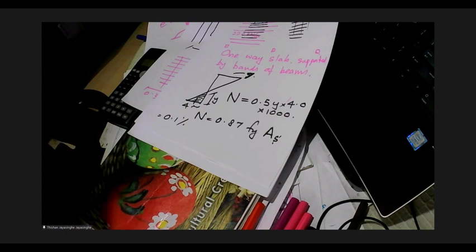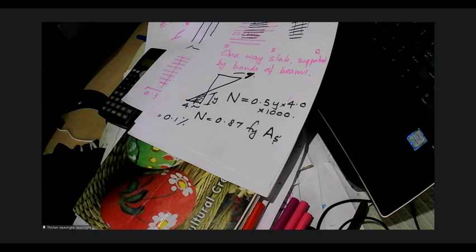But in addition to that, you have to see that the stresses are not violated in the sections, and it's effectively a one-way system. And if the stresses are violated, then you have to provide some extra reinforcement to carry those additional stresses. Is that clear, Bashika? So that's how you will design a two-way spanning slab.